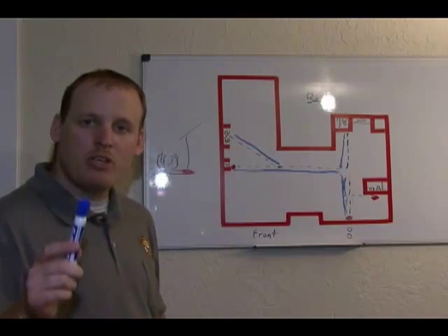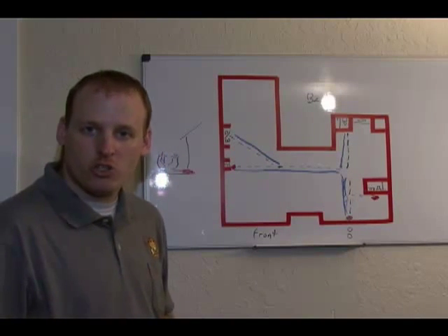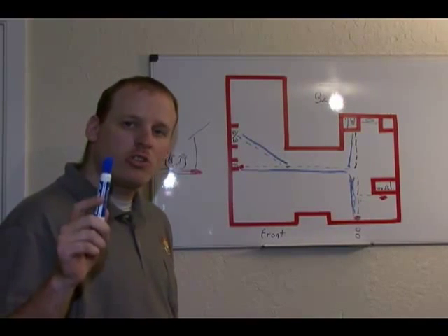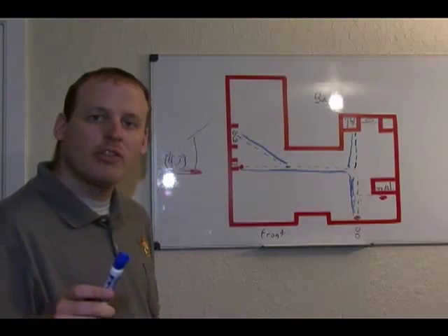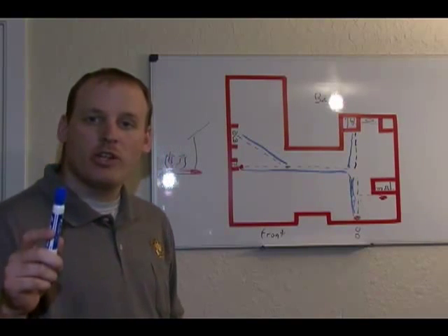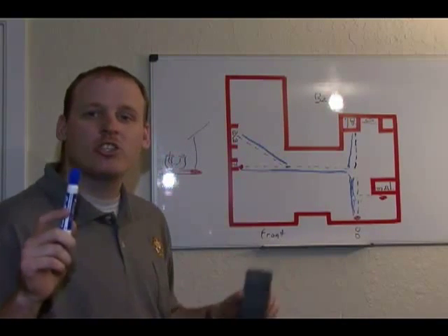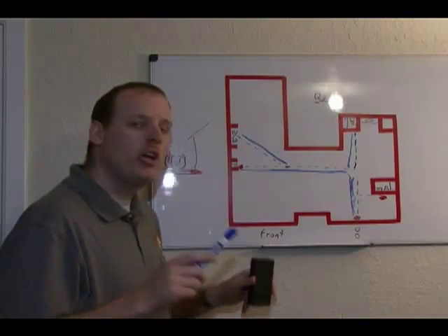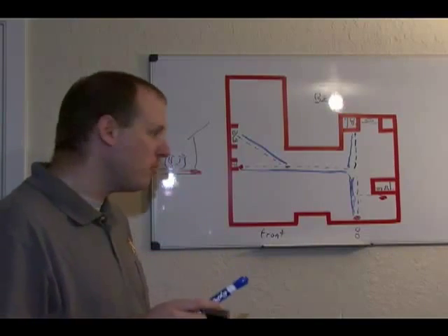Cameras should not be used as primary leak location tools. If you need a leak located, make sure you talk to the contractor you are discussing with to make sure that they do it. It's called hydrostatic sewer leak isolation. That's what we do: hydrostatic sewer leak isolation, where you're using test balls and cameras.